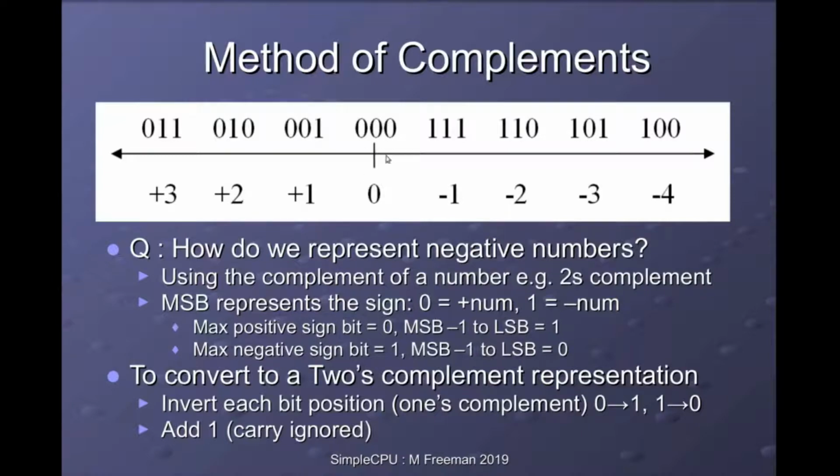Okay, so you can see here we go counting up: 0, 1, 2 and 3. Obviously you can't represent the value 4 because that would need to use that most significant bit, and as I said, using signed numbers, it represents the sign digit now. One thing to note, in 2's complement you always represent one more negative value than you do positive, because 0 technically is a positive number using 2's complement because it's got a 0 in the most significant